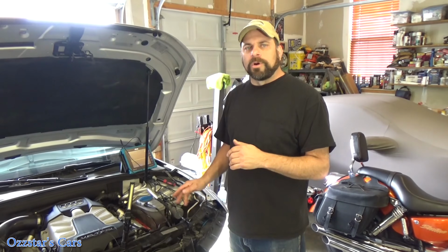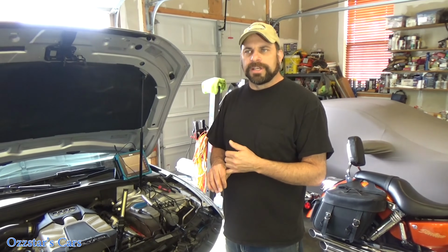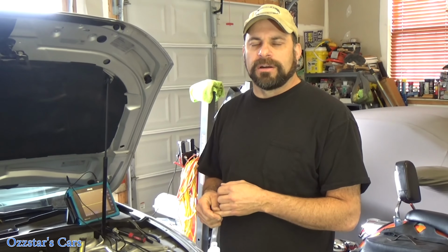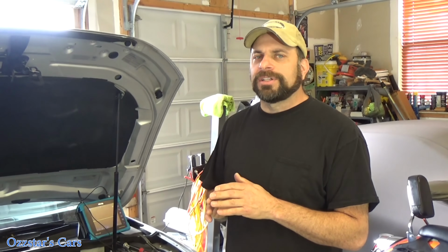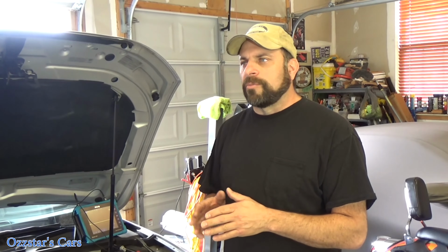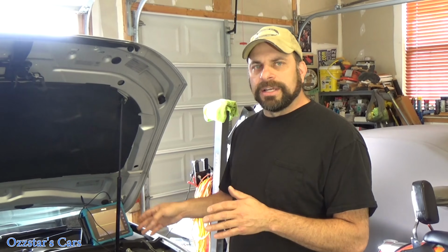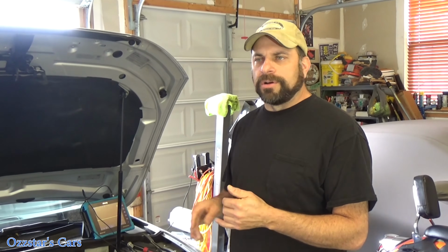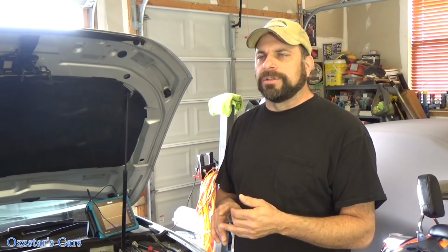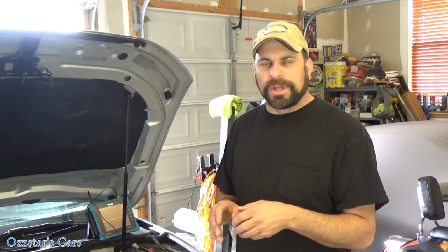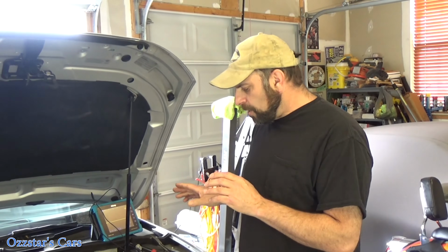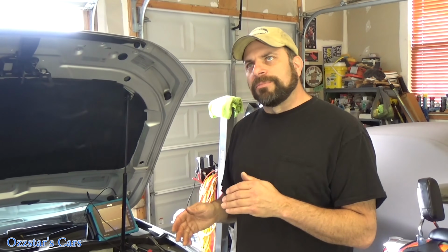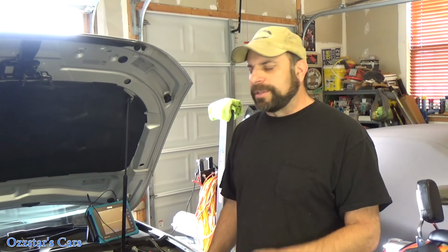Something that's important with that signal wire, I mentioned the 8 volts, is if you did not see 8 volts there, which like I said, it doesn't really matter, but it does. If let's say you saw 0 volts or something really low like 2 volts, then you may want to consider checking into the wiring as far as the integrity further, because there could be a cut wire, there could be some corrosion, maybe a rodent chewed through there or something and it's grounding out. So the 8 volts gives you a little bit of information, but it doesn't really determine that the sensor's bad.